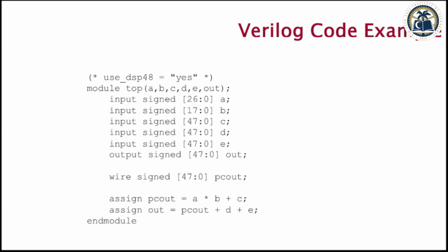For example, here is a code where sometimes you say, use DSP48, okay? And sometimes you say, no, don't use it, I want you to use my implementation of the multiplier and adder. So you say, use DSP: wherever there is an addition, put DSP48, and where there is a multiplication, use it.